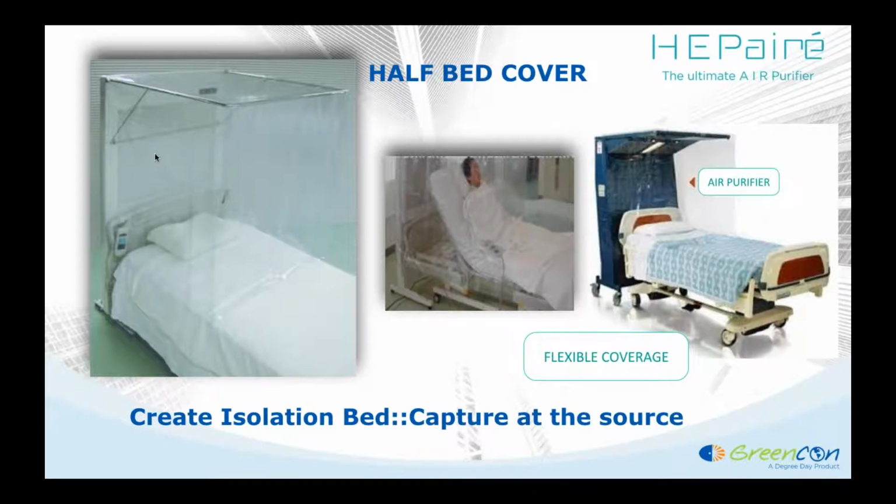What you see on the back over here is a supplier unit. I am feeding the air from a front discharge model into the place where the person is lying inside. Now, this could be a scenario like, say, an AIDS patient who develops COVID. You cannot have any outdoor air coming into his respiratory tract because he's prone to get any kind of disease very quickly. So you need to keep that person in positive pressure. You're pushing the clean air into that area, allowing the air suction below the bed, and sucking it back and recirculating within that space so that you are able to achieve that.